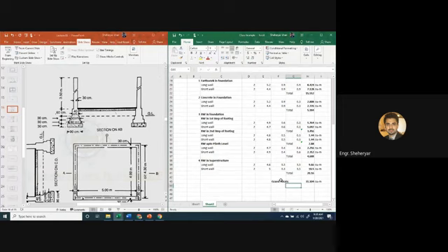I am saying that if there are 550 bricks in 1 cubic meter, so the number of bricks will be equal to 550 multiplied with the number of cubic meters. So it is giving you 17,107.2 number of bricks.